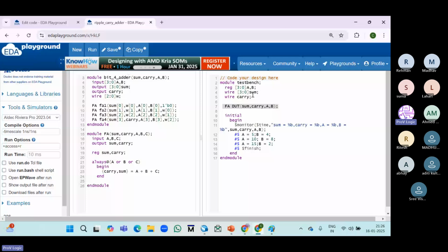So that's why we need to check full adder first and then top level. So full adder test bench is correct. A, B are the inputs, sum is the output, carry is the output, but a small change will be there. What is that small change? Observe the inputs and outputs here. The vector formats of input. Here we need to change the values, or else I'm just copying these, taking another module and commenting this.